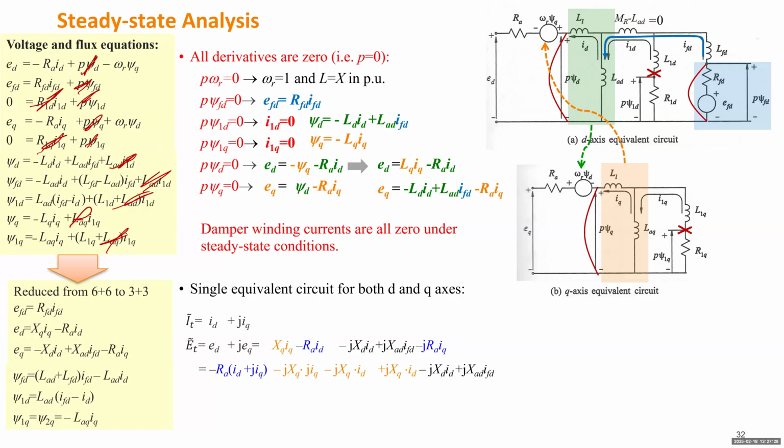Okay. Then for the X_sq term, which is the reactance multiplied by i_q, we need to create one item which is like X_sq multiplied by i_d, but there's no such item at all. There could be X_sd multiplied by i_d, but that is not X_sq multiplied by i_d. So we can create one item which is X_sq multiplied by i_d. And for this item, if you compare to the blue items on the resistance, we know the i_q component comes with an imaginary unit j.